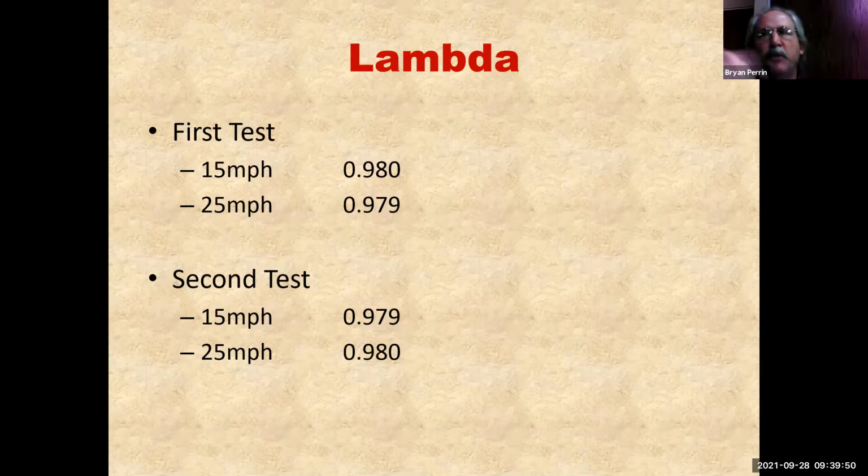So you see where tune-up, spark plugs, all those things, I shouldn't be focusing on, because if I can pick up 20% of converter efficiency or 30% of converter efficiency, I bet you I get rid of 10 parts per million. You see how that graph is really important to understand. I'm running rich. Running rich is going to explain CO because we know CO is a lack of oxygen. I'm going to lose converter efficiency, which could explain why I'm slightly failing on hydrocarbons. So don't get distracted by the hydrocarbons here. Don't even get distracted by the CO. This is all about fuel control at this point. I don't care about anything else.